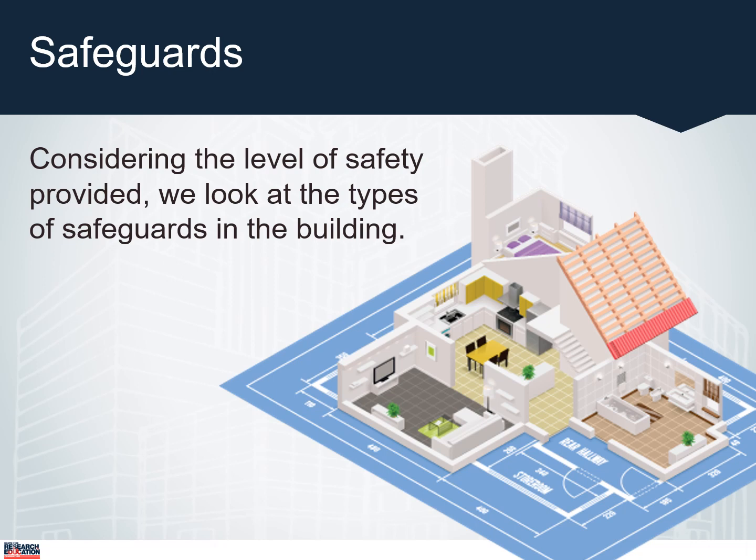Does the building provide compartmentation or fire separations? Does the HVAC system provide any benefit or smoke control, or will it spread smoke and toxic gases throughout the building? Are smoke detectors included in the HVAC system ductwork to shut down the units when they are conveying smoke? Is there a smoke control system in the building? Are there dead-end corridors that could result in people unfamiliar with the egress routes being trapped in an emergency? What are the interior finishes in the rooms, in the corridors, in the stairways? What's the occupancy? An office represents less risk to occupants than a nightclub.